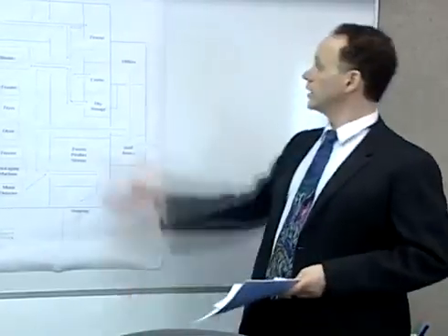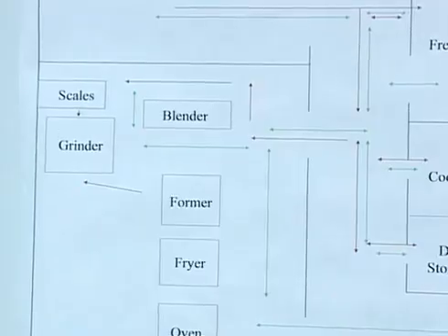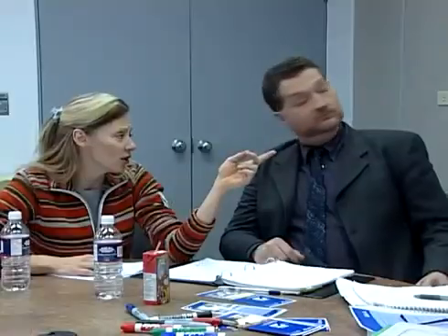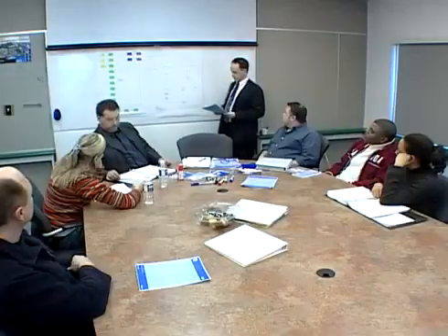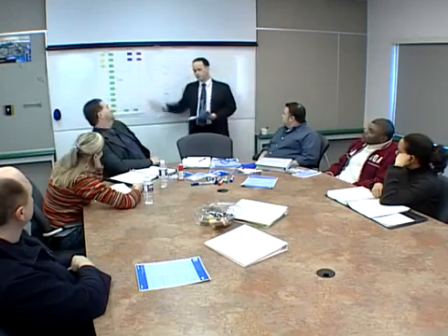Enough detail should be included to help you in your hazard identification. Next, create a plant schematic. This helps identify rooms and their function, also product flow and employee traffic. This is very useful in identifying and assessing potential hazards such as cross-contamination. That's how we figure out where the problems could be.